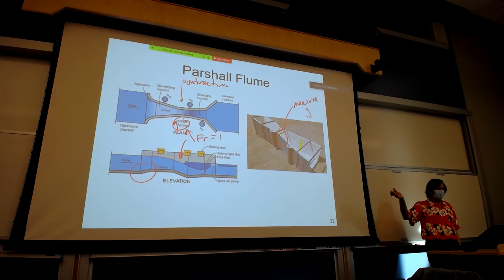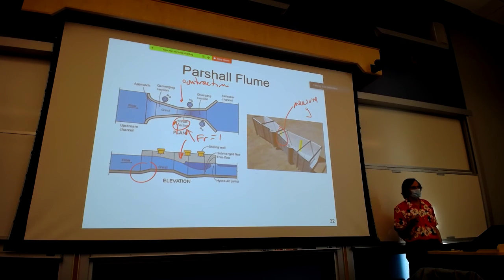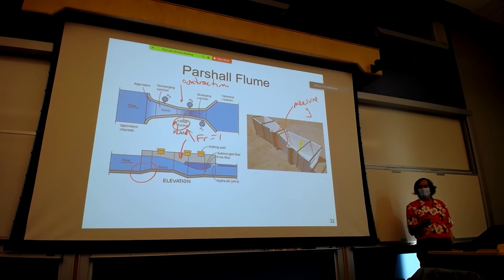At the Stormwater Center on campus, we use weirs at the end of all the pipes, so we can measure the inflow hydrographs to all of our systems, and we can measure the outflow hydrographs to all of our systems. In natural channel systems, for example, a 20-foot wide river, one, you just can't put a structure out there. You can't just put in a weir because you want to. You would need permits to do that, even temporarily.